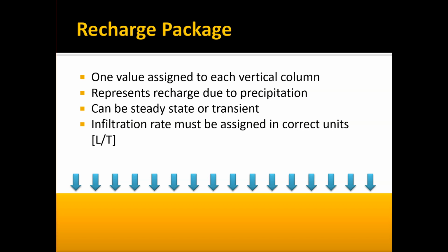So for example, let's suppose that, how do you come up with a recharge rate? A really common metric that we use is say 10 to 20% of recharge is a good rule of thumb to remember. Or excuse me, 10 to 20% of annual precipitation will often find its way down. It could be less than that, it could be more than that, but that's a good rule of thumb to start with.